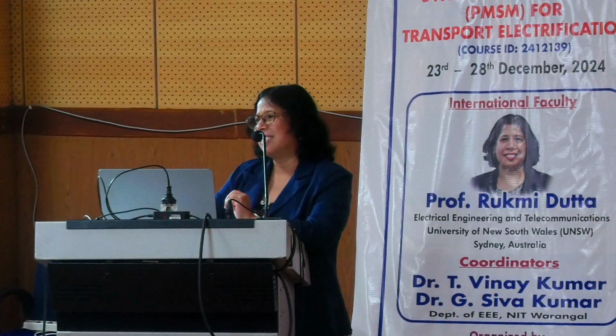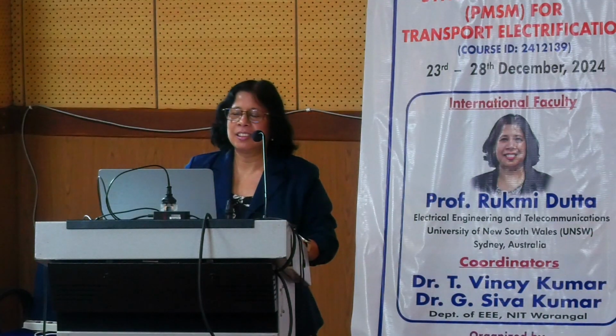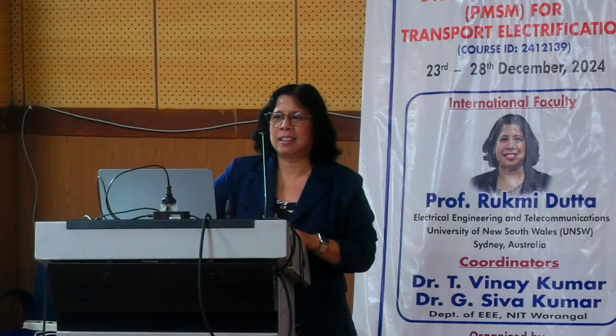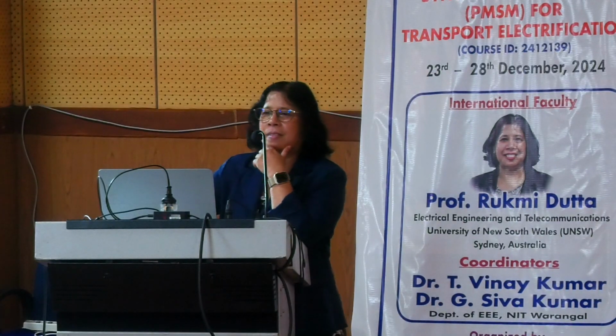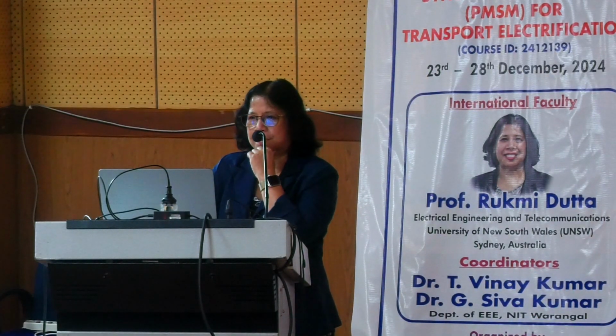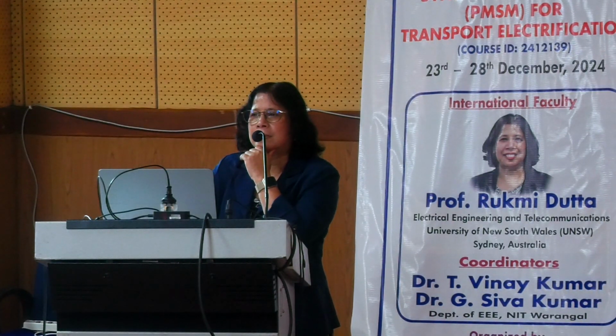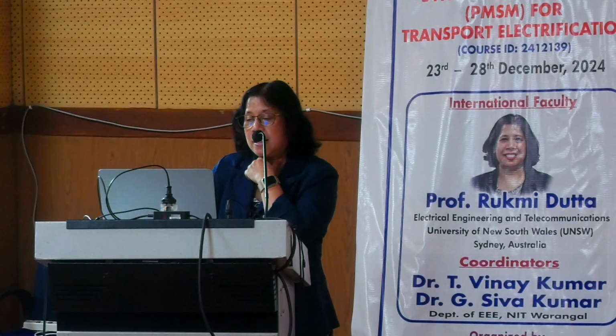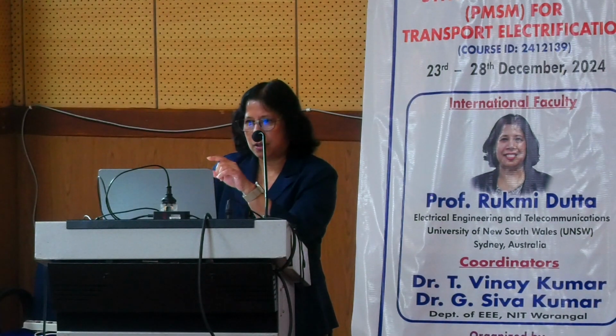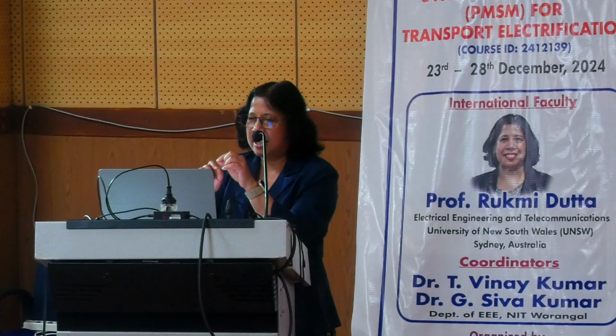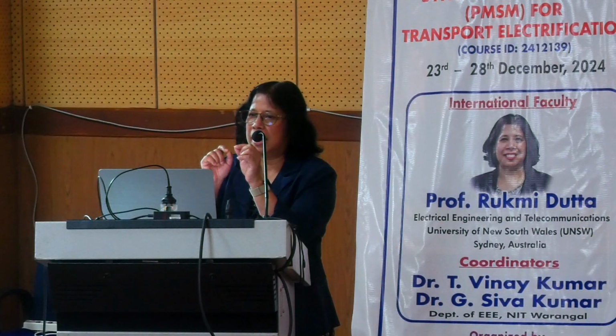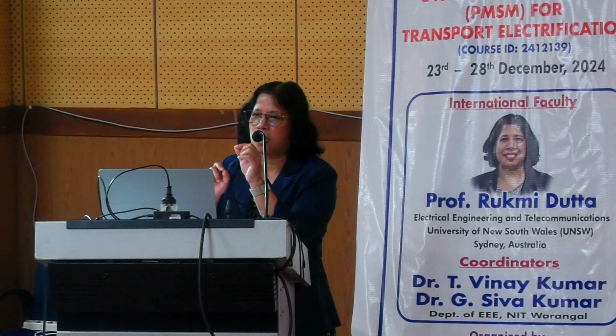Ma'am, what is your suggestion to start a PMSM? Whether I use a VFD drive, the technique that you are saying, V by F control or damper winding for FOC, etc. What is your suggestion? If you have a sensor or encoder, you have no problem starting, because if you are doing FOC, V and F increase in proportion. If you have zero speed, your frequency is zero and voltage is zero.